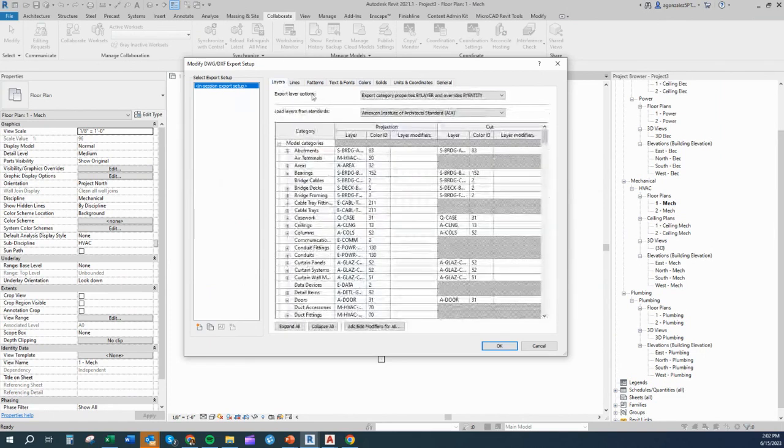And if you go back in here, you have the export layer options. The first one means that a Revit element with view-specific graphic overrides will return those overrides in the CAD application, but will reside on the same CAD layers as other entities in the same Revit category.